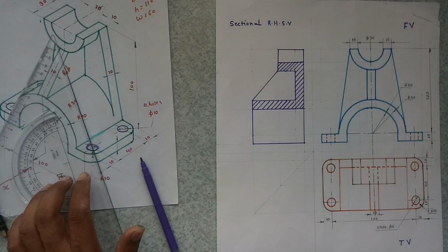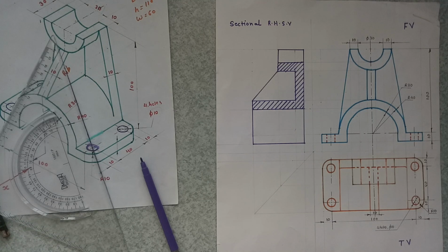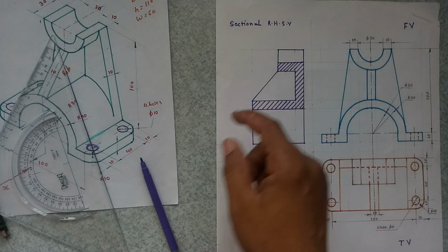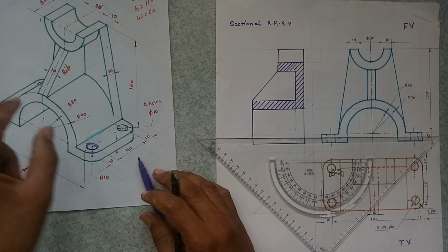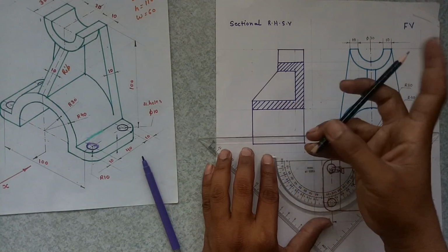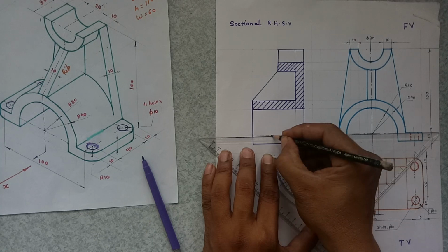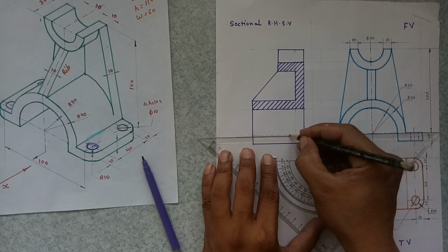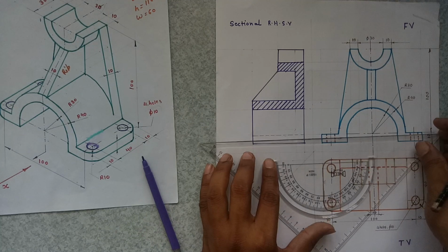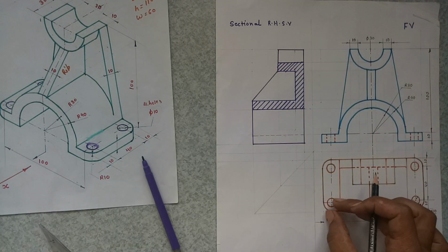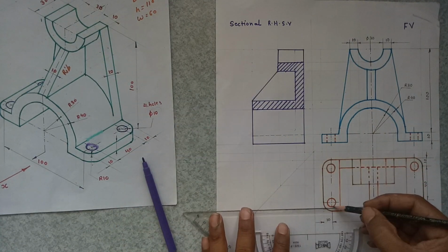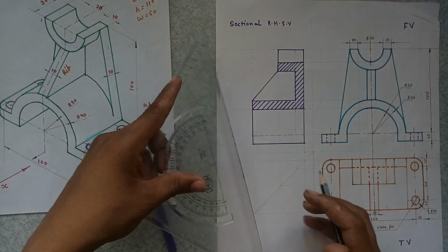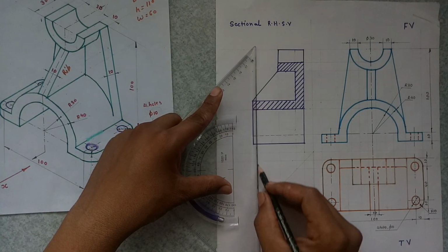So this will be the sectional right hand side view, and we have discussed that in the sectional view we are not showing the hidden outlines, but in the part outside the section, here we can show the hidden outlines of the backside part, this part over here, because here we are not showing the section. And the hidden outlines of the circle also we can draw, projecting from the top view here like this,